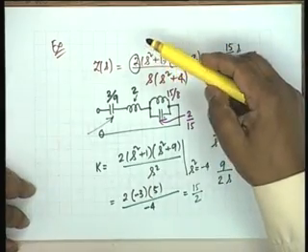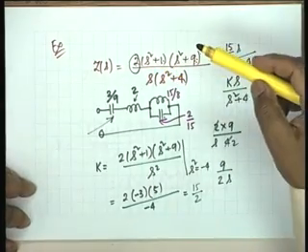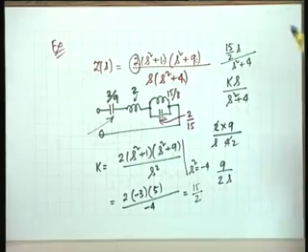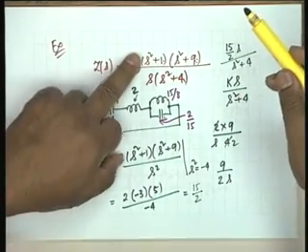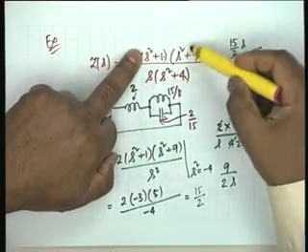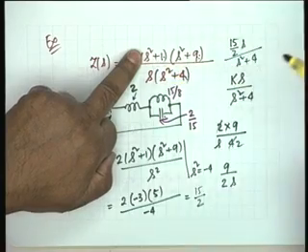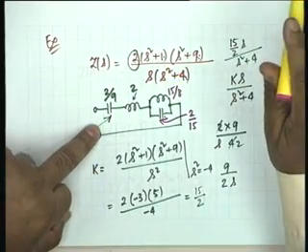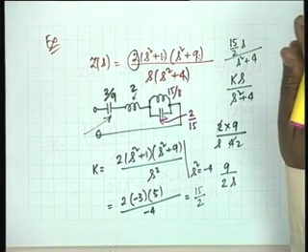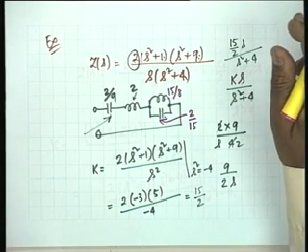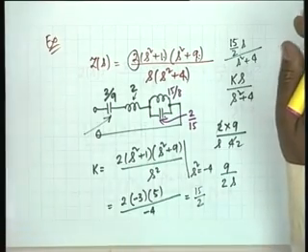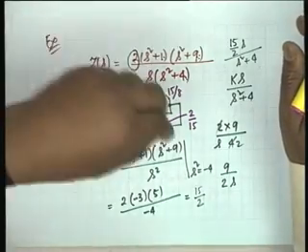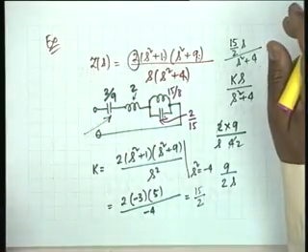Then instead of handling such large numbers with fractions and all that, we could have simply ignored it and obtained a realization of this with nice numbers. Finally, after I get the network, I can change the element values. How do I change the element values? Multiply k with inductor and divide capacitor by k. That's right. So the multiplying constant will multiply the inductors and divide the capacitors.